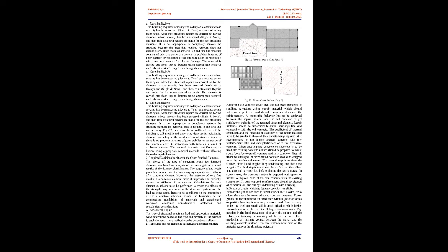D. Case studied 4. This building requires removing the collapsed elements whose severity has been assessed, severe to total, and reconstructing them again. After that, structural repairs are carried out for the elements whose severity has been assessed, slight and none, and then non-structural repairs are made for the non-structural elements.